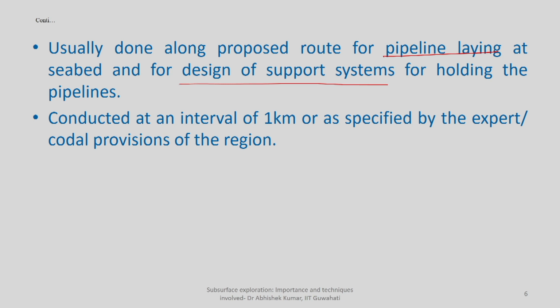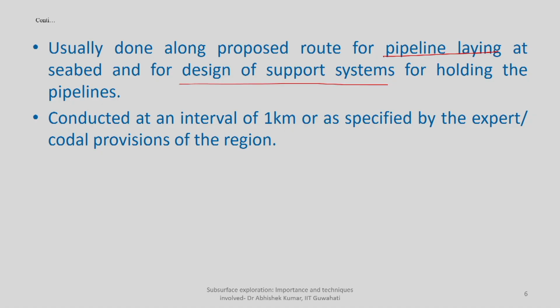Again, it is conducted at an interval of maybe 1 kilometer, or if there is too much variation in topography or too many obstacles, you can reduce the spacing of the shallow geotechnical investigation interval, or as specified by the expert. Generally, experts have an understanding of a particular area in terms of obstacles, topographical changes, and geomorphological changes also.